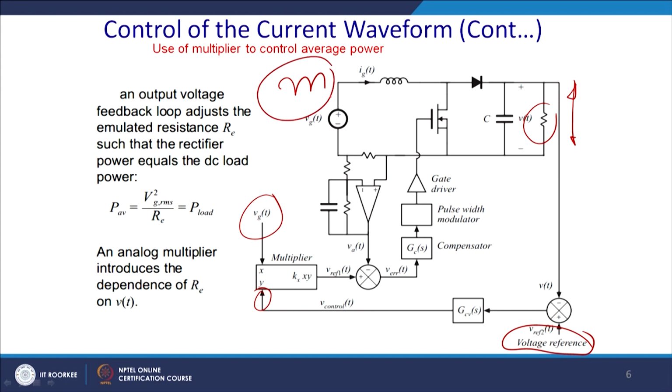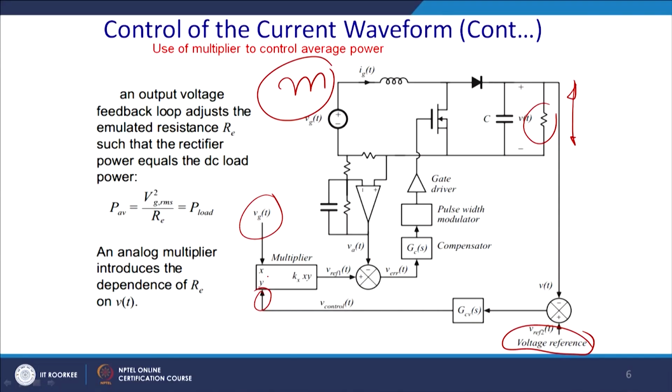Please mind it, this rectifier does not have a capacitor in the output, thus we have a rippled DC. That will be multiplied and you get some reference voltage that will be compared with the reference current multiplied by some constant. So ultimately the current flowing through this part is the input current to this boost converter.